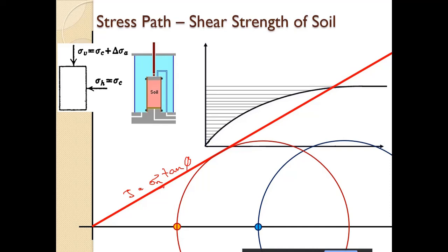So this is the Mohr-Coulomb failure envelope, and the Mohr circle and stress state in the soil, sigma 1 dash and sigma 3 dash, has reached the failure state, and this is twice the inclination of the failure plane, so twice theta. So this is 45 degrees minus phi by 2. All right, so that is the failure plane.